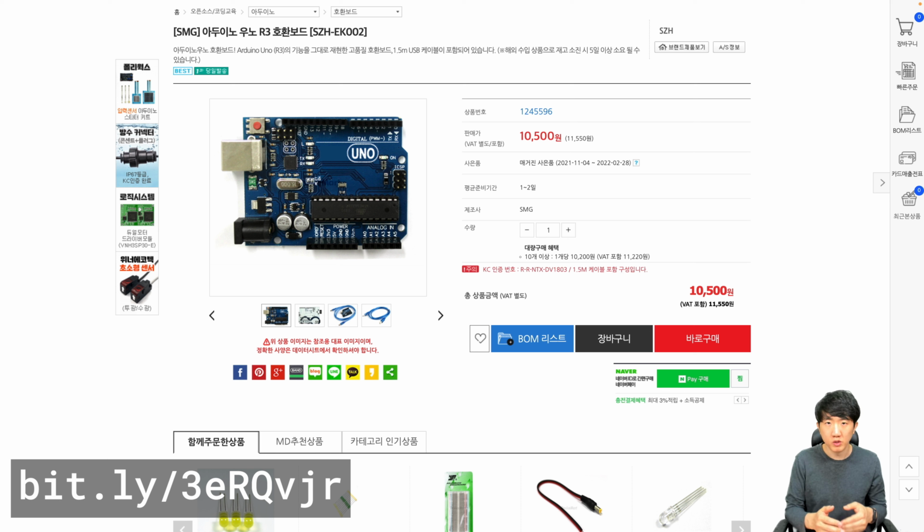In a way, it's similar to UART communication. And the key point to remember is that you need to check the datasheet carefully. Communicating is not that difficult, but when you look at the datasheet, you may find that each sensor has a different protocol and different checksum methods, and these can vary slightly. So if you can resolve those parts, you will probably be able to perform I2C communication directly without any trouble.